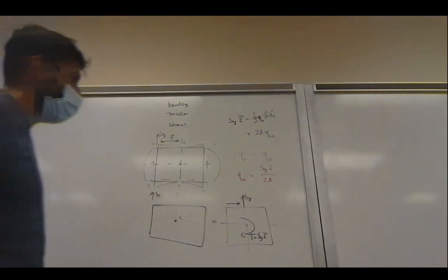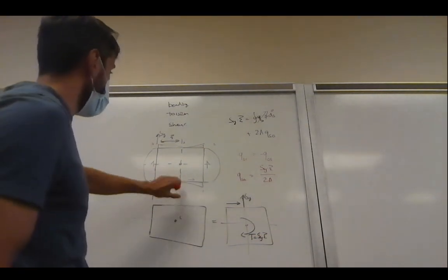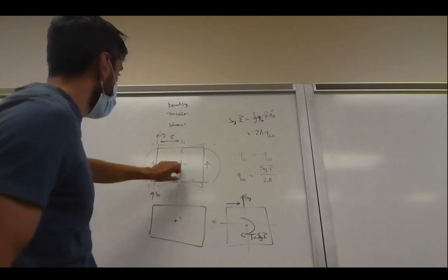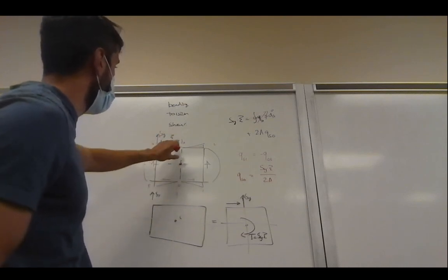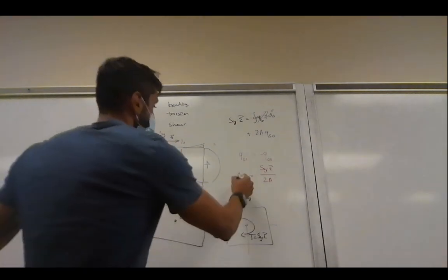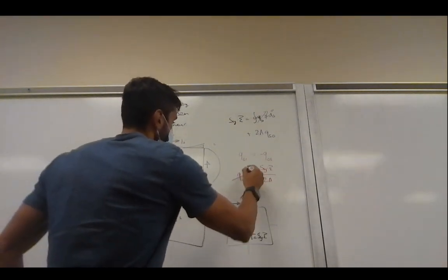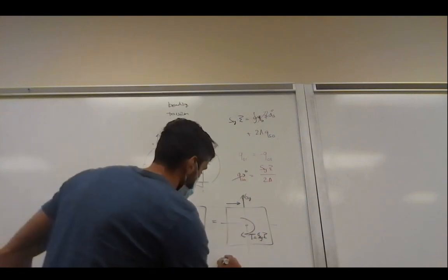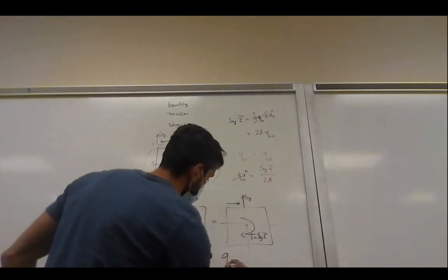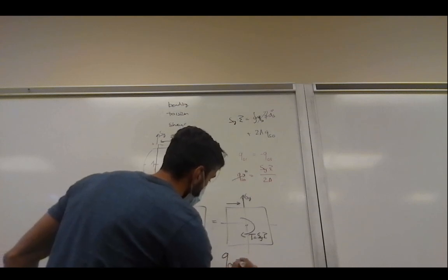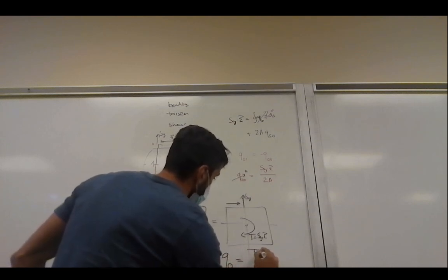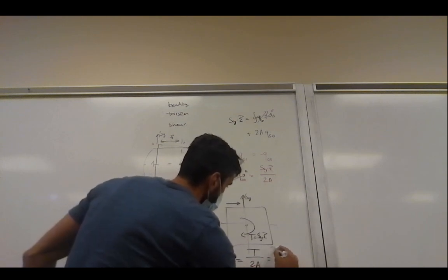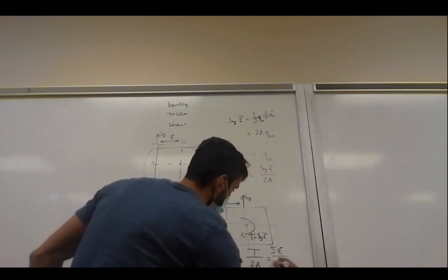So if we now do the shear flow equation, we get the same thing, we make a cut, but now we can argue that the location of the cut and what we take the centroidal axis from basically means that the correction shear flow is equal to 0. And this torque now adds a new q, say q0, equal to T over 2A. And T was equal to Xi times S.